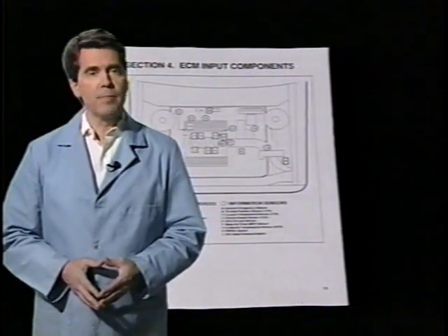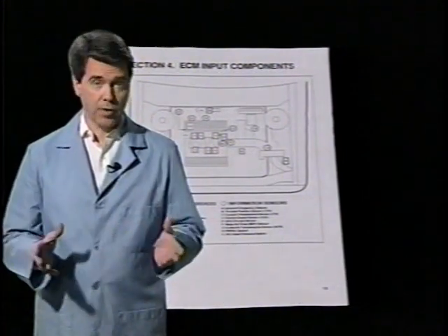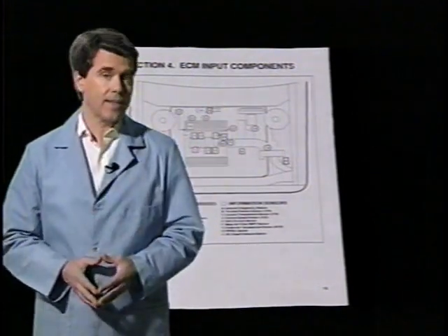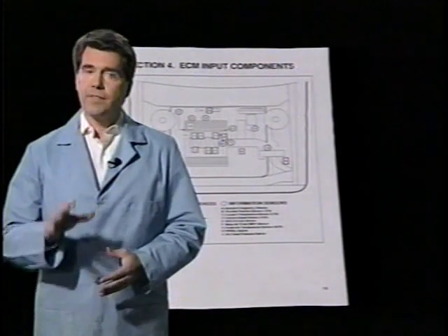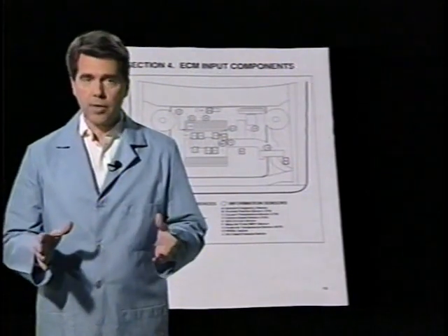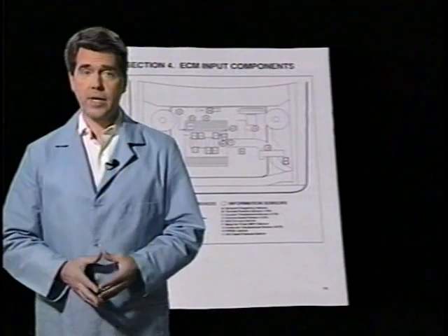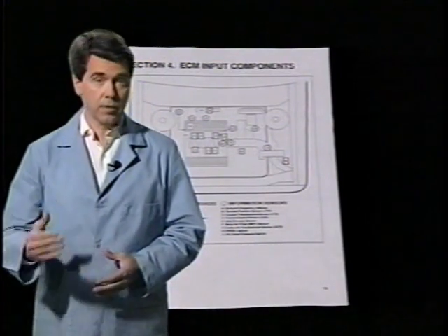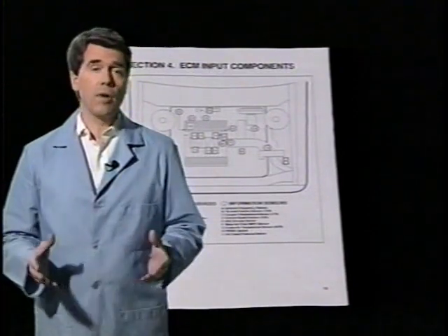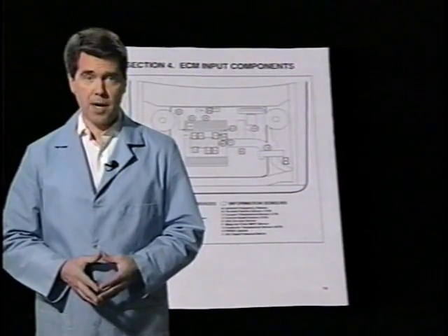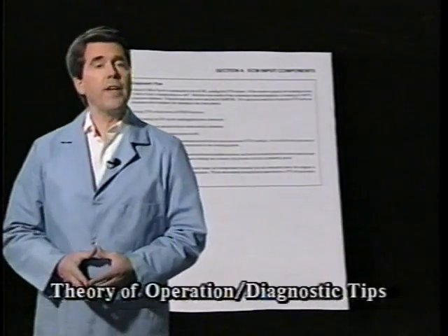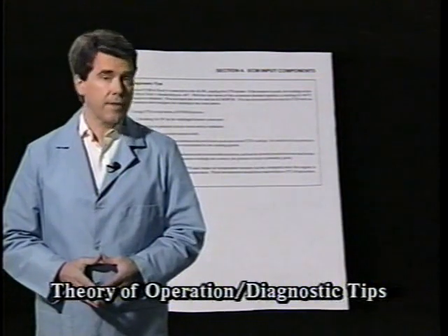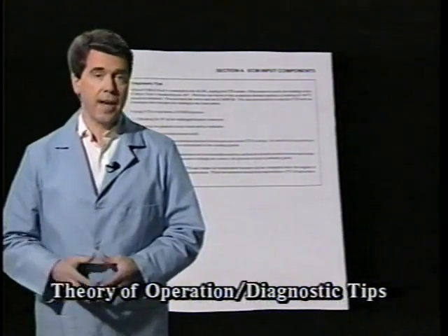It's important to remember that an ECM-PCM, as a computer, commands its output components based on what the inputs are telling the ECM-PCM. If an ECM-PCM controlled component is not functioning, it could be the component itself, the ECM-PCM, which includes the PROM or MEMCAL, or the inputs to the ECM-PCM. For each of the common sensors, the reference manual has a section explaining the theory of operation and suggested diagnostic tips.